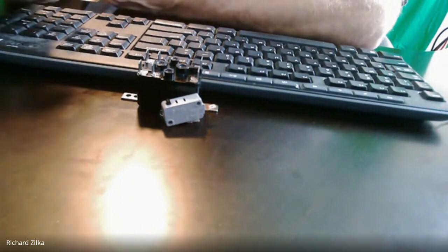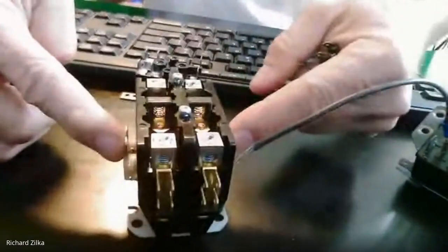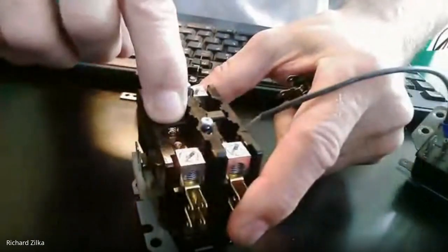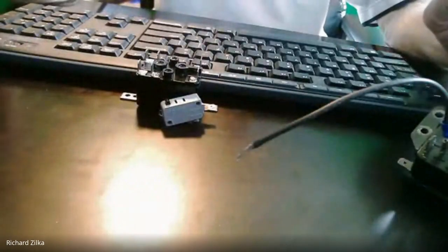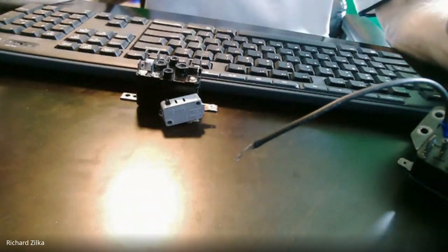Now, we want to do that when we check, like, if I want to check this timer motor, I'm going to check the motor for resistance. If I'm going to check this relay or contactor, what we call the coil, which is this side and this side, where when we give it power, the bottom part of this is a magnet, it pulls this switch down. That's got to have some resistance. And that's what the needle moving said, but it also gave me an audible tone. And that's called a continuity tester.